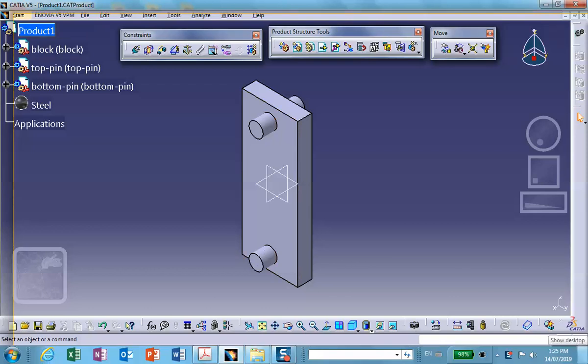Okay, this is the video segment for repeating chapter 14 where two planes of symmetry are used. In the earlier segment, I clamped the two ends of the bottom pin and pushed the two ends of the top pin up by some amount. I would like to repeat the same problem, but using the two planes of symmetry that exist, namely the YZ plane and the XZ plane. The first thing we need to do is to go and cut this into pieces.